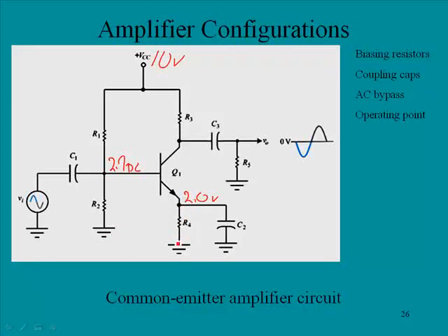That would cause a current to flow. That current would go through to the collector, and it would drop a voltage across R3, and so we'd have a voltage drop here, and let's just pretend that we have 5 volts on the collector right here. So these two are setting the biasing for the base, and then R4 and R3 would establish the values that you would see at the emitter and the collector. Well, really the collector, because the voltage here on the base actually determines what the emitter voltage will be here, because there's going to be a 0.7 drop right here.